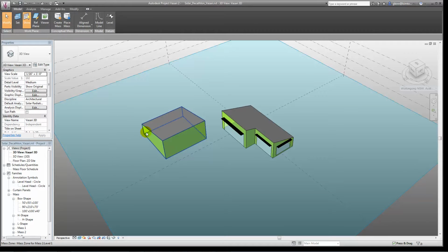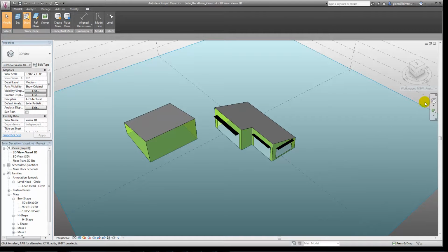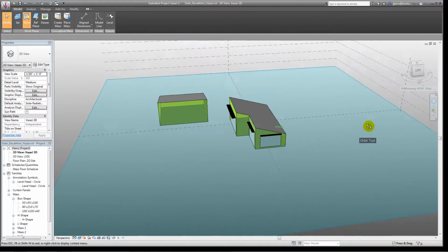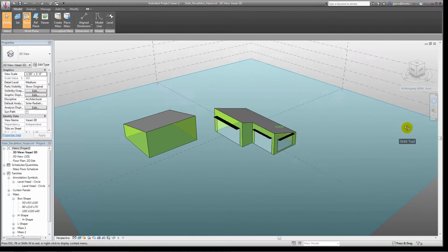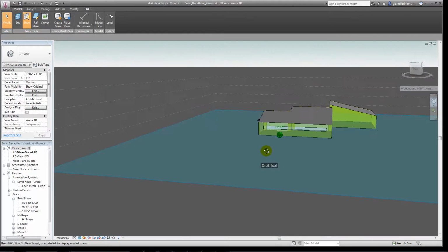The idea is that once you've gone ahead and created a form, we can start adjusting the characteristics of that form pretty easily. For example, you'll see on my little model over here, I've put some windows in, in some specific locations. Vasari tends to think of things in terms of different ratios of window to wall. So you'll see that on the north side, I put some big windows where I think I might want to try to capture some sun throughout the day. On the south side, I put some smaller windows, on the back of the house.